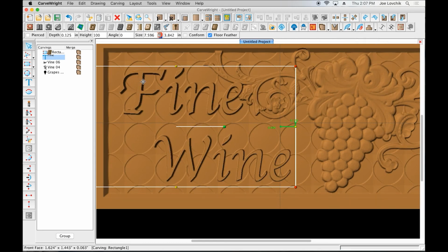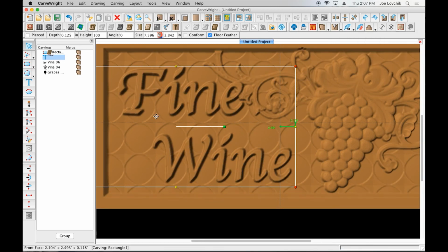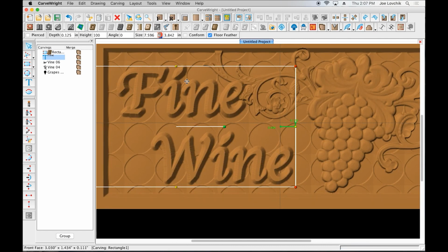Small adds a very slight taper. It's usually just enough to accommodate the taper of the bit, and it will work in most cases where you don't want to necessarily see the draft. Medium gives a little bit more of a beveled edge, which actually starts to take on a decorative quality. And then draft is very extreme and can be a very nice technique, especially on very fine text. You can get this really nice bevel, outside bevel pattern.